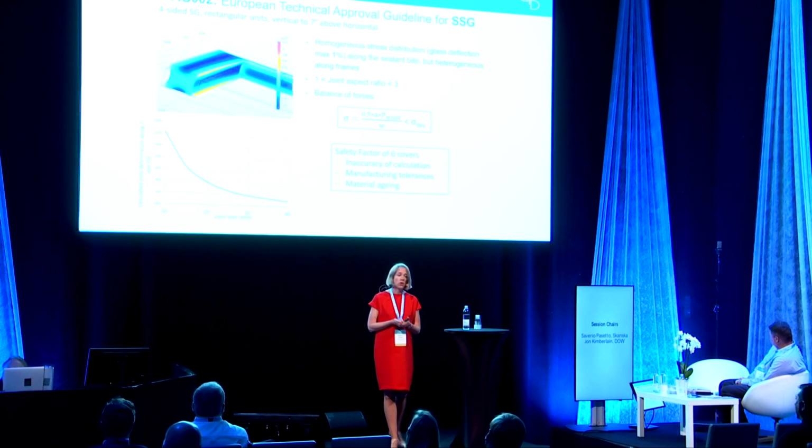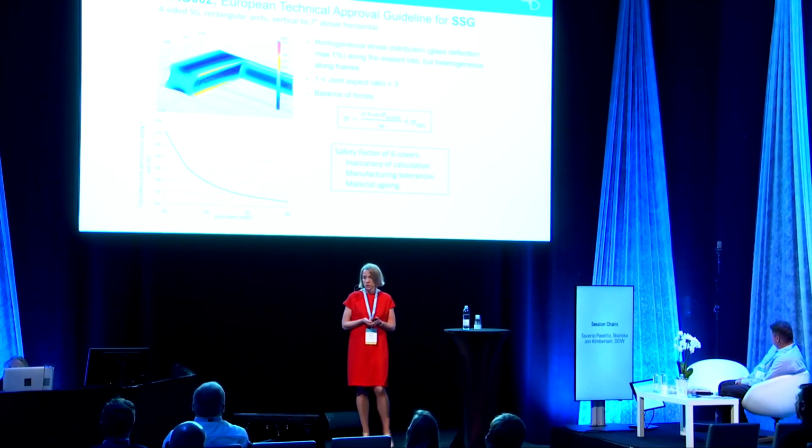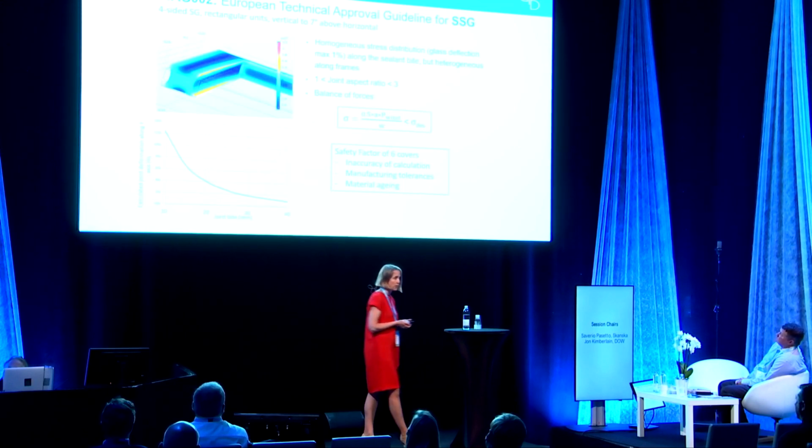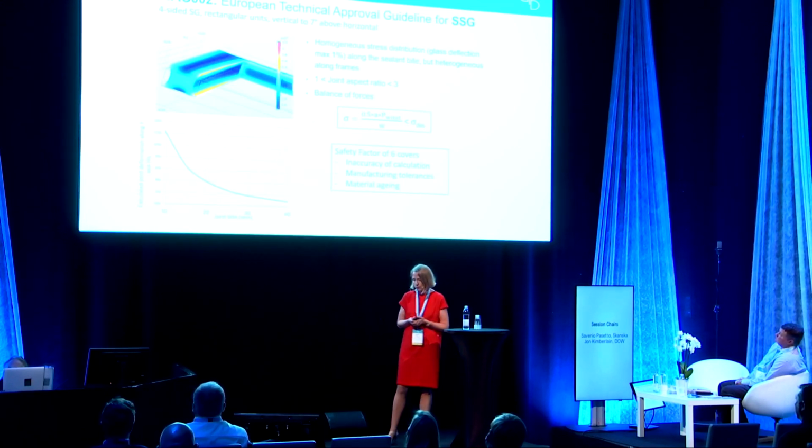And by performing a very simple balance of force, it's possible to derive this famous equation that gives you the bight as a function of the small panel dimension, the wind load, and the design strength for the silicone. They used a very large safety factor, compared with safety factors used in other industries, to cover all these simplified assumptions of the calculation, to cover manufacturing tolerances, and to cover natural aging. Even if silicone is a very performing technology, there is a slight aging happening.